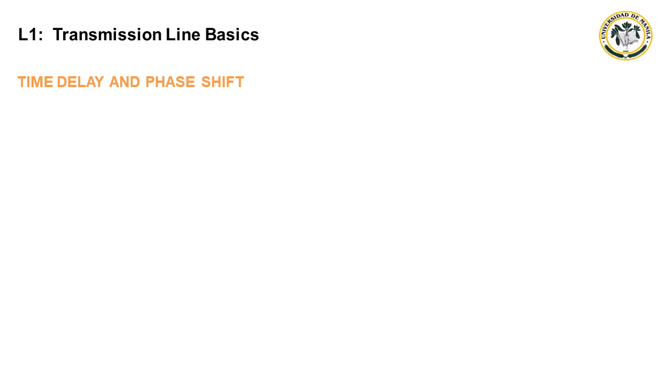The amount of delayed time is a function of the line's inductance and capacitance. The opposition to changes in current offered by the inductance, plus the changes in the discharge and charge time of the capacitance, leads to a particular delay. A transmission line used specifically for the purpose of achieving delay is called a delay line.